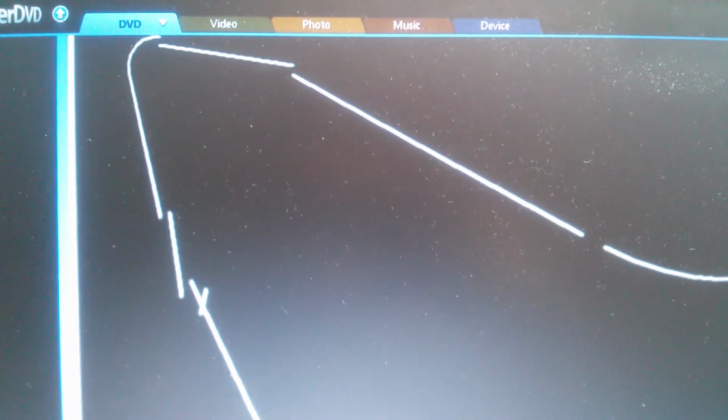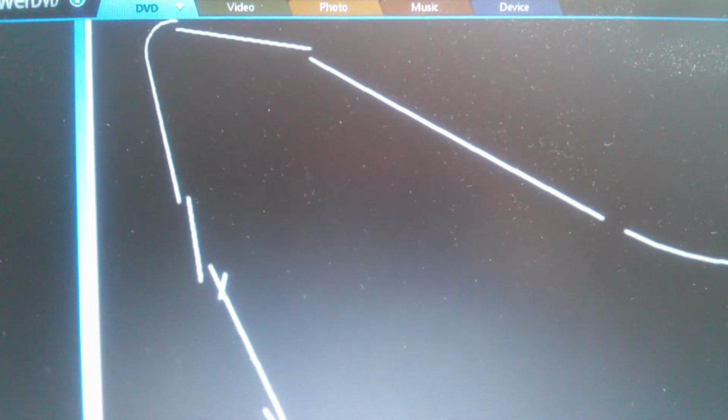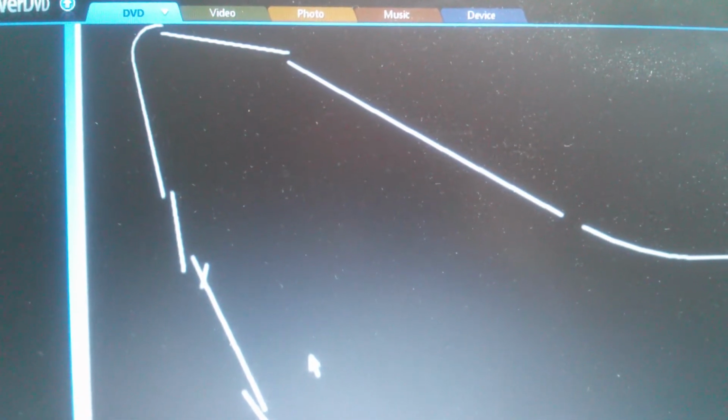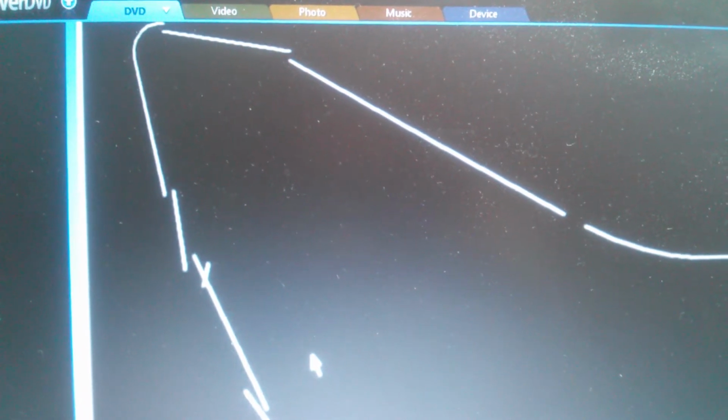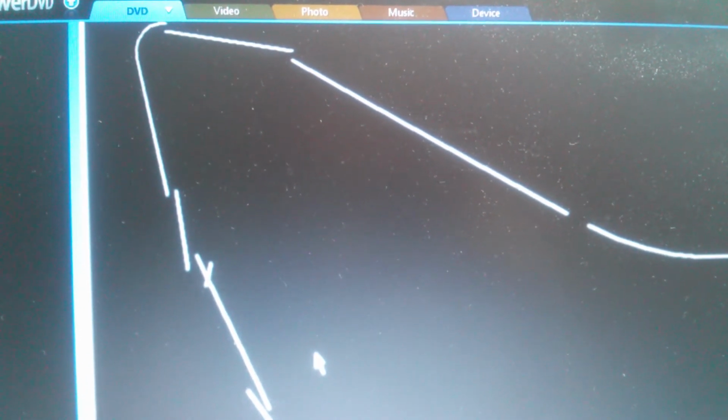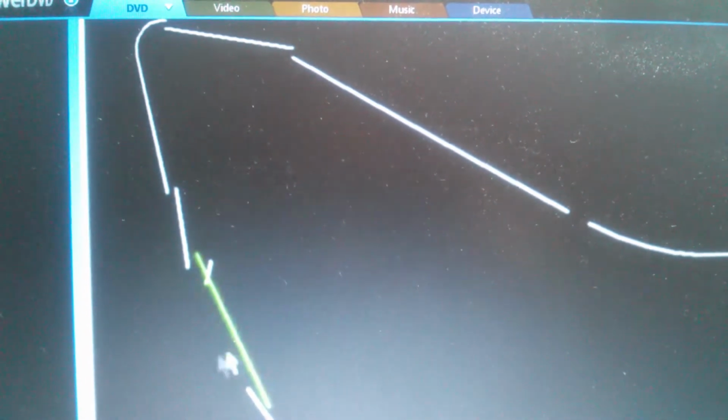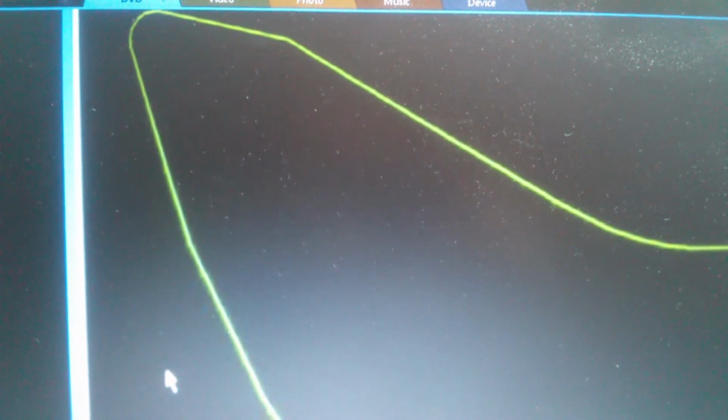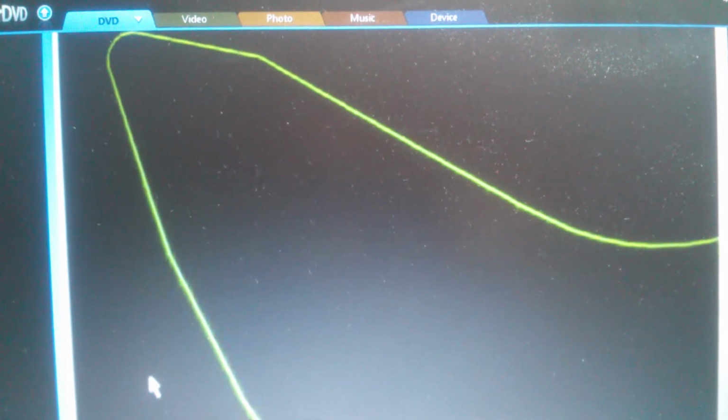If we could tell the machine to cut the shape out just the way it is now, it would have to cut each little piece one at a time, and they would likely not be cut in order. What we really want is for the program to link together all of these pieces and form a continuous path that the machine will cut along. When I select a piece and choose the link command, all of the nearby pieces are joined together and the extra overlapping pieces are erased, leaving a perfectly cleaned up part.